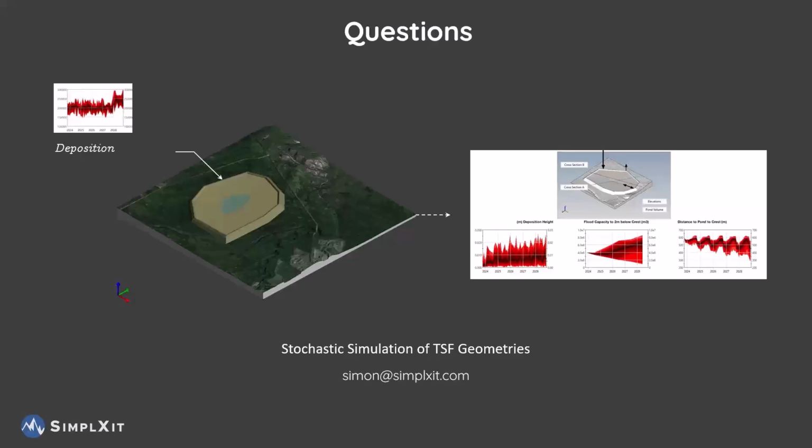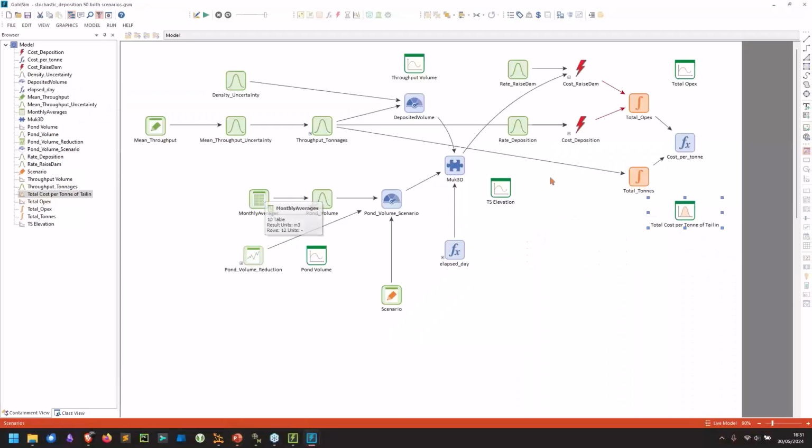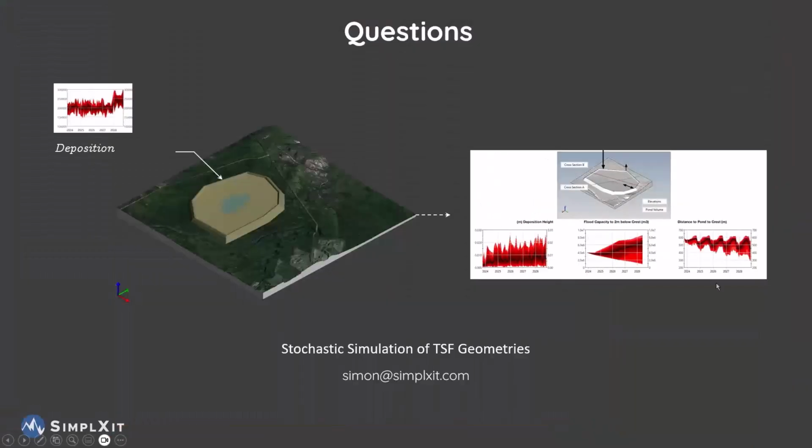In this model, I used the model from e-water, the Australian e-water, to fit a distribution, and ultimately I've got a time series which has 2,000 years of rainfall. And I just changed the, what is it called again in GoldSim? Right, time series shift, to shift annually in between each of those years that have been simulated outside of GoldSim. So it's not actually a stochastic model within GoldSim, it's external.